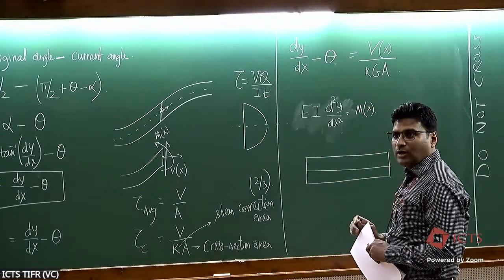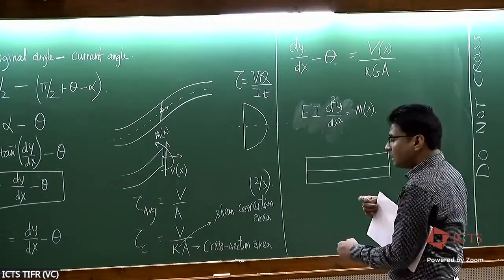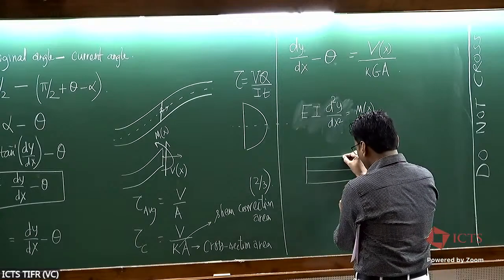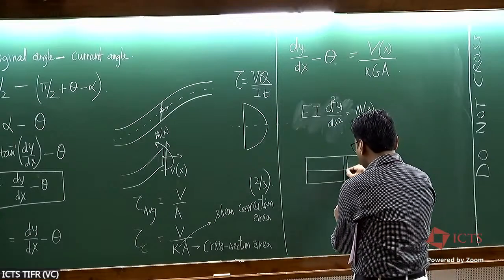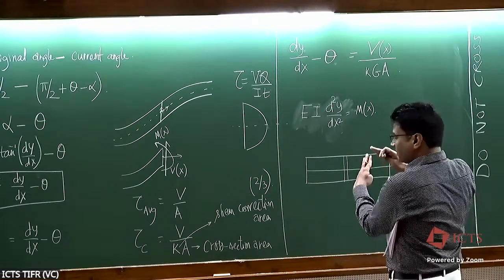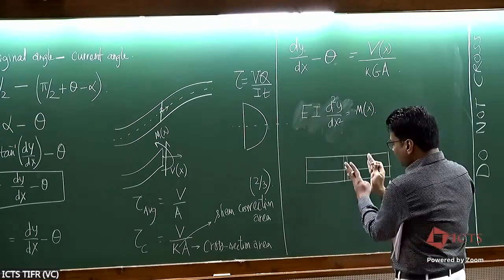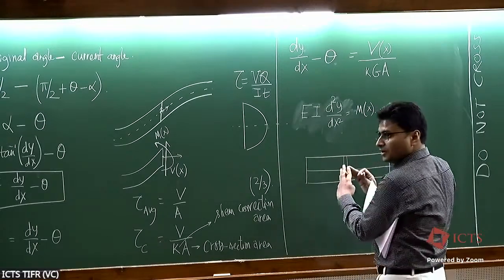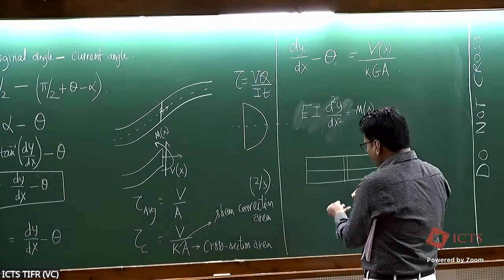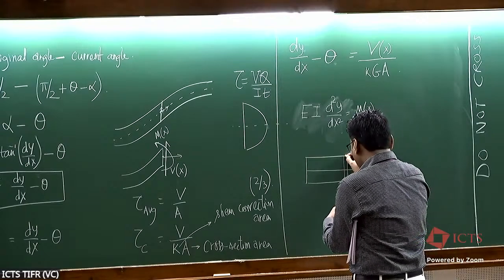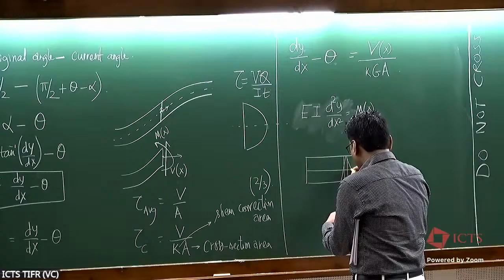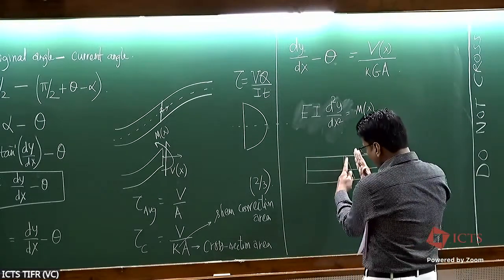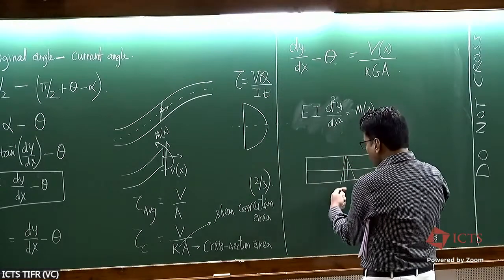But in bending, why does bending moment really arise? It is because if you look at two neighboring cross sections, as they bend, on the top side, for example, they are pushing each other. On the bottom side, they are pulling each other. So perhaps it's going to become something like this. Only then the top will be pushing each other and the bottom will be pulling each other.